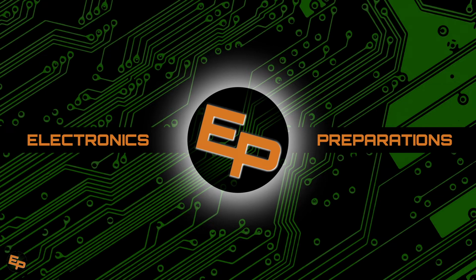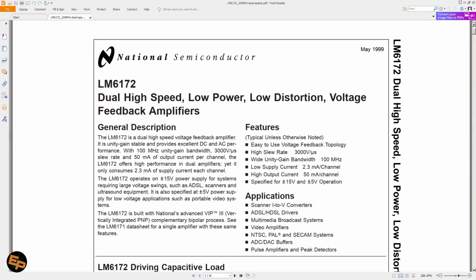I will need this in order to make some experiments with some transistors, and I will want to see their switching ability. I will post a video soon about that. But now I want to show you the circuit because, in order to test how well a transistor switches, you need to have a square wave with as short rise times and fall times as possible.